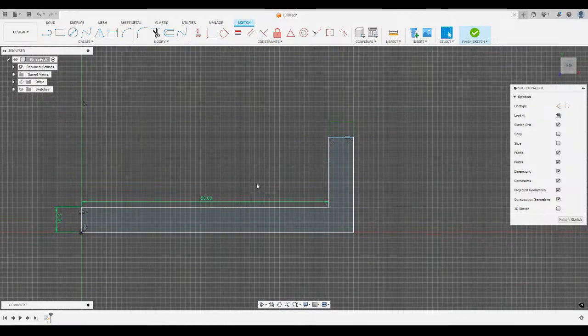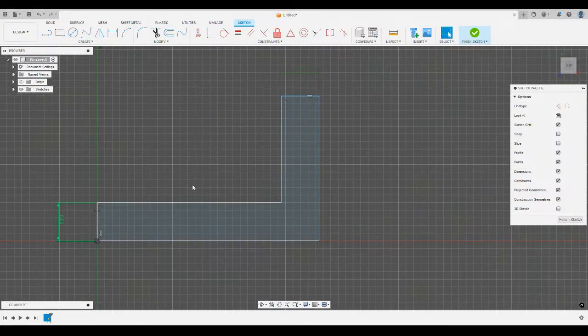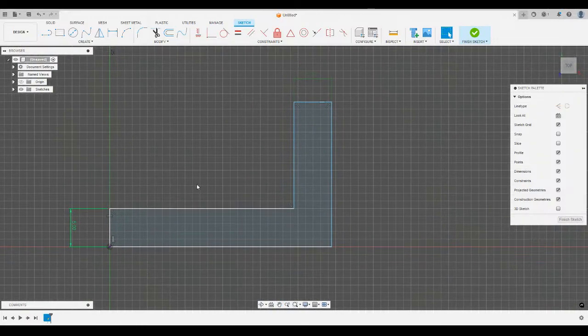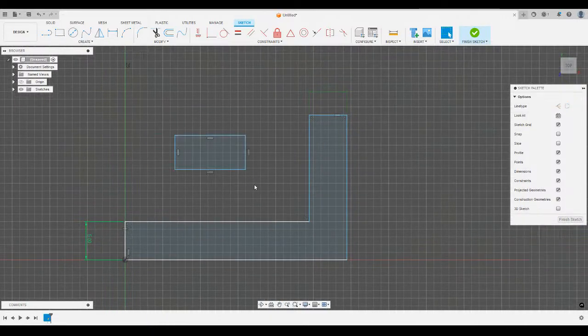And then you'll notice, I'm going to undo that. Actually, I'm going to delete that. So one thing I glossed over: in Fusion, when you draw a sketch, I'm going to draw a rectangle here real quick. So I have this rectangle floating here. All of its lines are blue, and that means that they are not constrained, meaning if I click on the corner and drag it around, it'll move, or if I click on and select the whole thing, I can just move the whole thing. It's not constrained in any way. It's just completely free floating. I'm going to delete that.